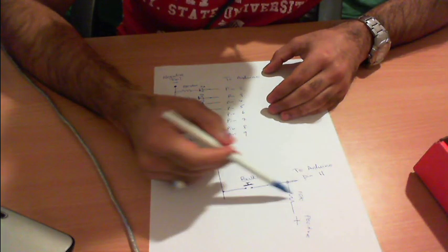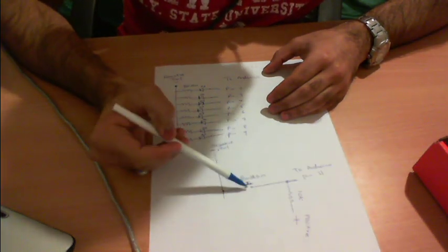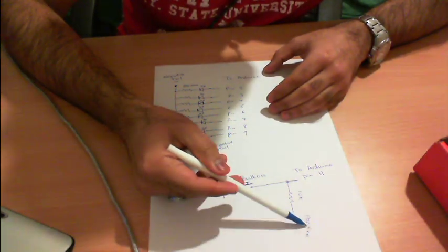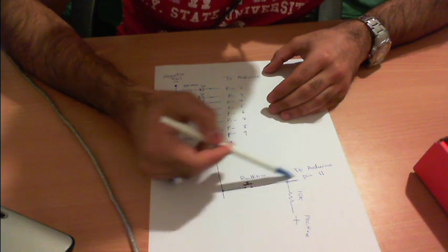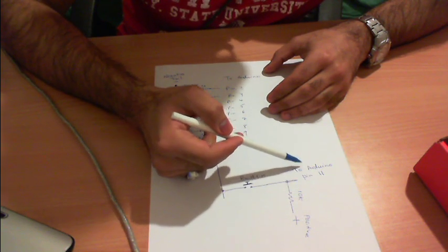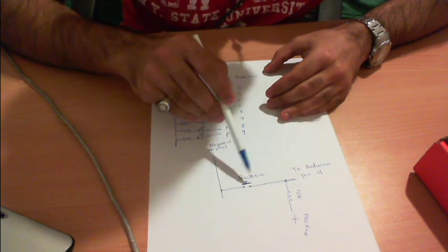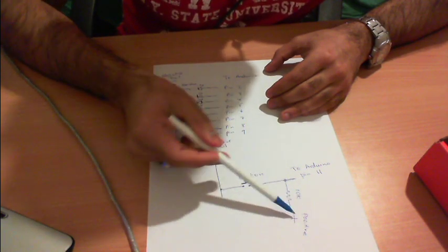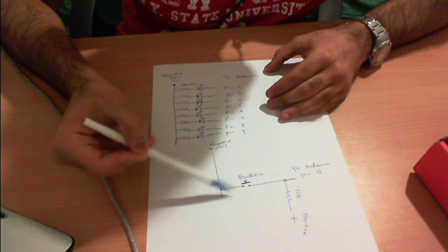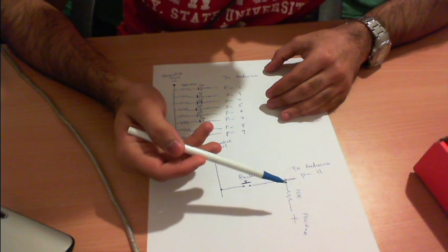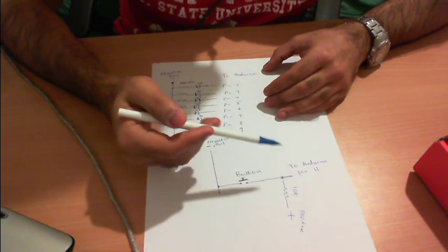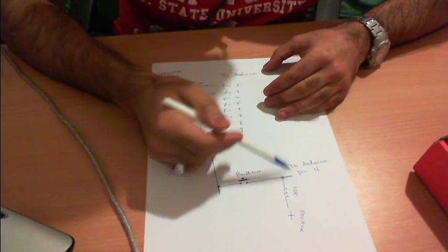So what this will do is it will ensure that in the situation where the button is not pressed, we will always have a constant 5 volts going to pin 11 on the Arduino, so it's going to be a constantly high state. And then as soon as we press the button, it's going to complete this circuit, and obviously the voltage is going to choose to go through to the ground rather than to this side, so we'll have a low. So this will give a more reliable high or low reading on pin 11.